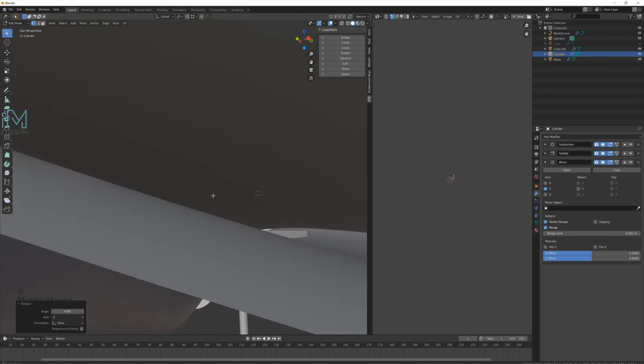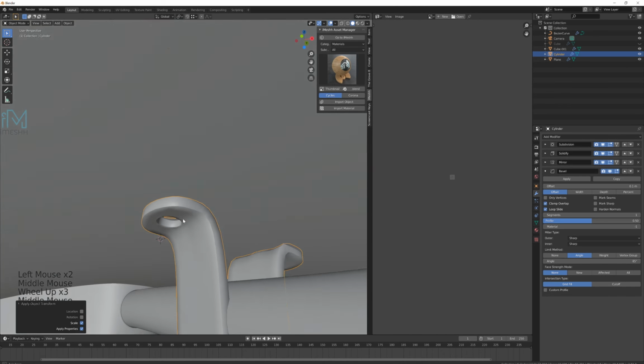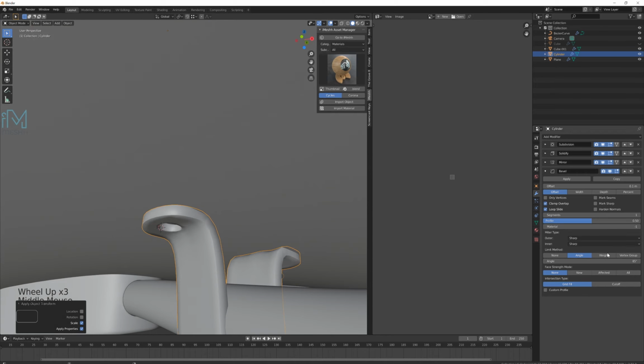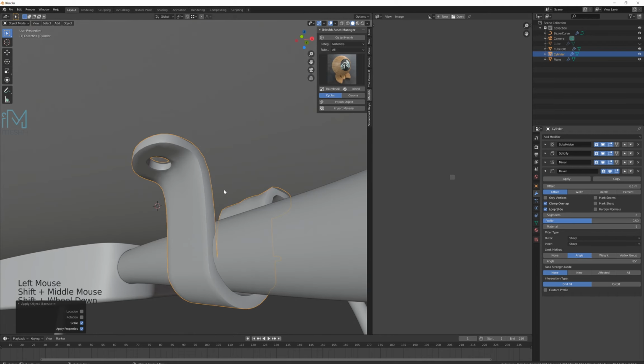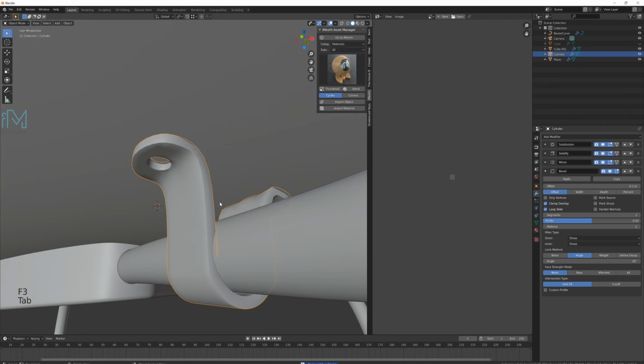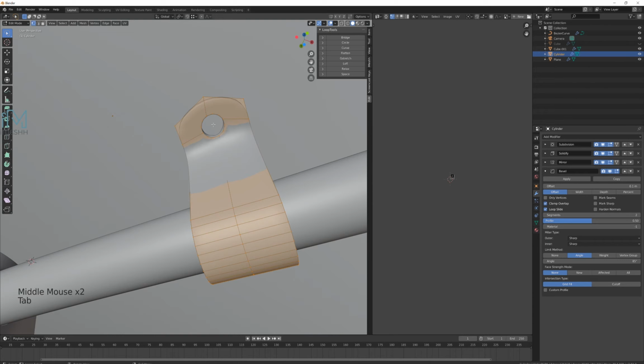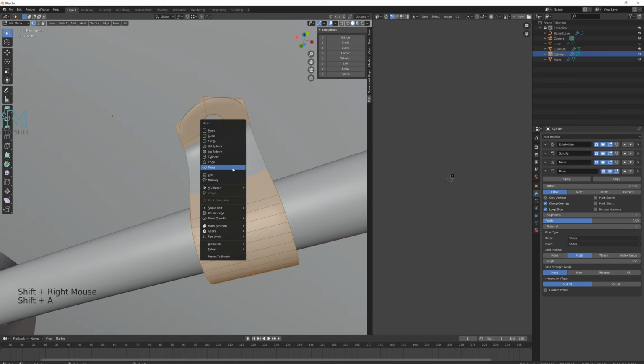I do right click and click shade smooth, and we'll want to add a little bit of a bevel. Apply the scale and set it to angle and set it to 85. Okay, and then give it one more. Okay, now what I want to do is go into the shape and click Shift and right click and do Shift A and add a...